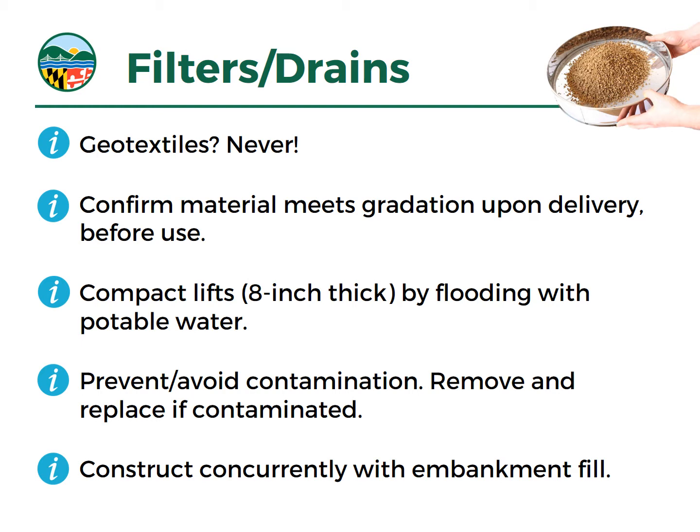We had a project recently on a large new dam where the engineer and the quality control person both noticed that the material that was supposed to be clean concrete sand was a little dirty, and they tested it before use. They rejected about 5, I believe, dump truck loads of this filter material because it blew past the percent passing 200, the clays and silts specification, as required.